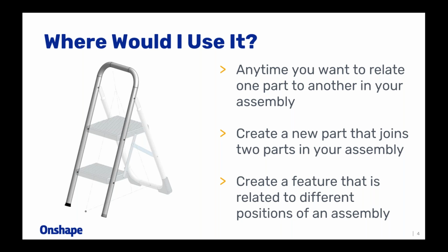If you're designing those link arms one at a time, you would have to take a whole bunch of measurements to figure out values and all those types of things. Whereas designing them in context, I can literally just convert entities and extrude, very simple. So creating new parts is just as good a reason as editing existing parts in context.